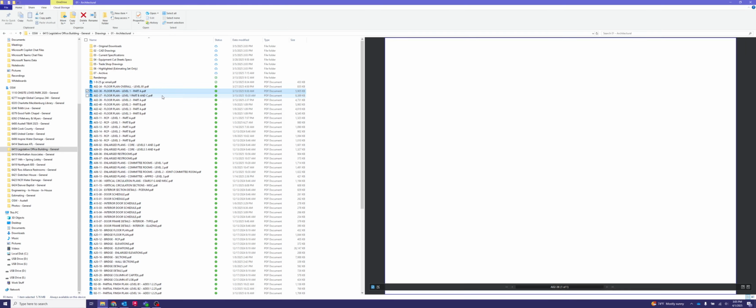They do give you overall dimensions of that room from what it looks like. It looks like we're dealing with, from wall to wall, a room that is 10'4 1/8" by 8'7 7/8" on this side. The cabinets don't actually run all the way to the wall, so as you probably can guess, there's going to be a finished end on this side. The side is butted to a wall, so most likely we will be putting a filler in this area here, between the cabinet and the wall.